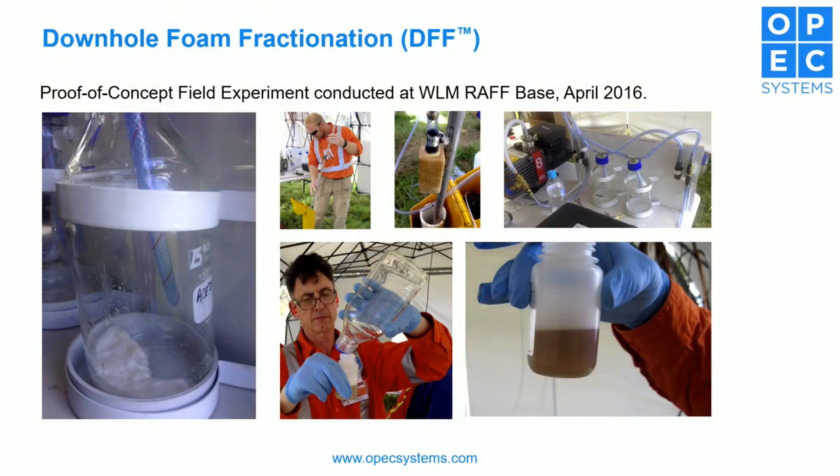One of the areas, as you said, mate, where we first started was downhole foam fractionation. We have worked in the downhole foam fractionation area since 2016, just doing experiments on whether we can effectively use interconnected circulatory wells to create a permeable reactive barrier of air beneath the surface on the downstream gradient of a PFAS contaminated site, to progressively harvest that primary fractionate while we're in the ground.